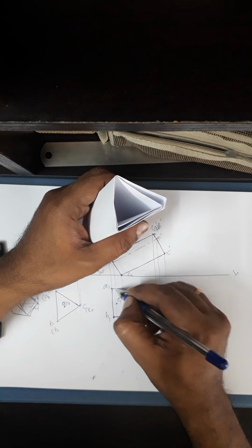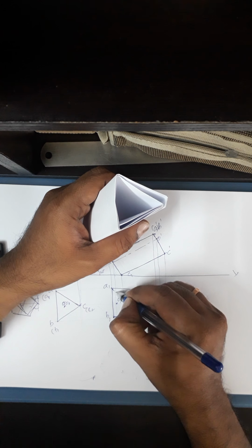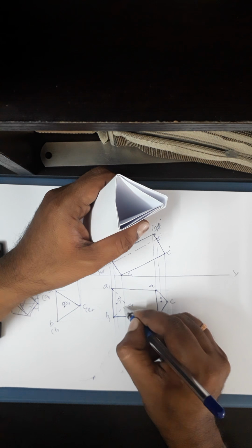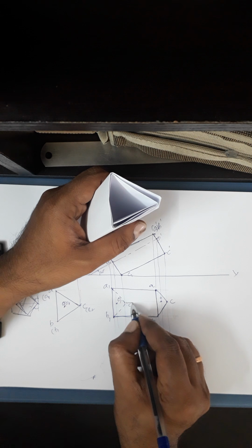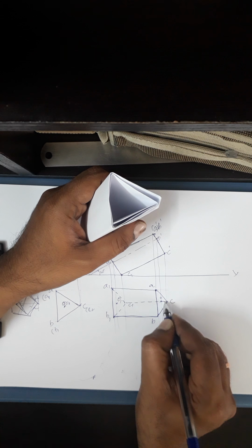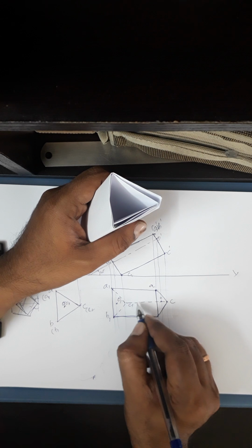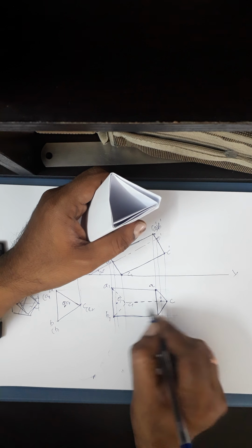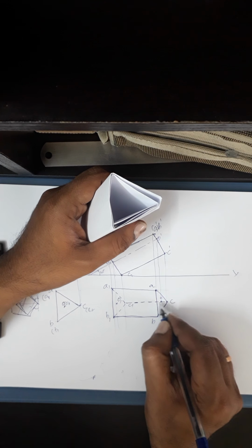So in that case I'll go for drawing all these edges with a dotted line. So again this becomes a dotted line. So C1 is a dotted line, invisible edge. So give preference to the edge, okay, equally spaced, equal length line. So even though the axis coincides here, you need not give the preference to the axis, go for this.